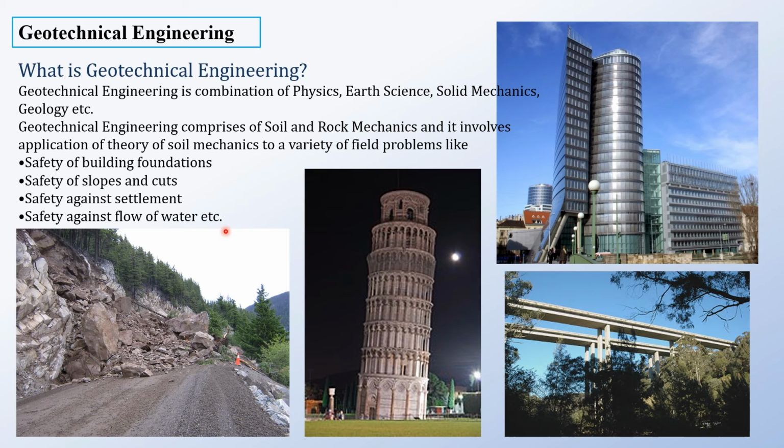Next is safety against flow of water. So as a part of the syllabus, we'll be studying what is seepage analysis, etc. Why it is studied is, suppose you want to build a dam, and if it is an earthen dam or a rock and earth dam, of huge height, and then if the water is stored in rainy season, and there is a lot of permeability, that is flow of water is possible in the dam, then the whole of the water will be discharged on the other side easily in very little time without serving the purpose, because the dam is constructed to store the water so that it can be used for months together, almost year long, so that when the next rain comes it will be able to fill the dam.